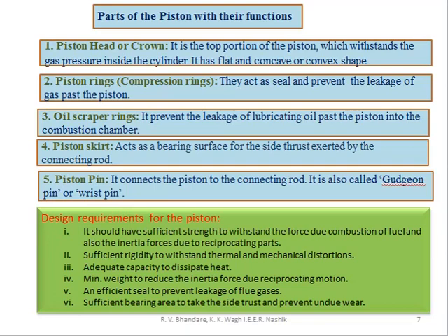the combustion chamber. In the upward stroke, it will provide lubrication to the cylinder, and during the downward stroke, whatever the excess oil, it will absorb that oil, so it will not leak into the combustion chamber. So these are the functions basically performed by the oil scraper rings.